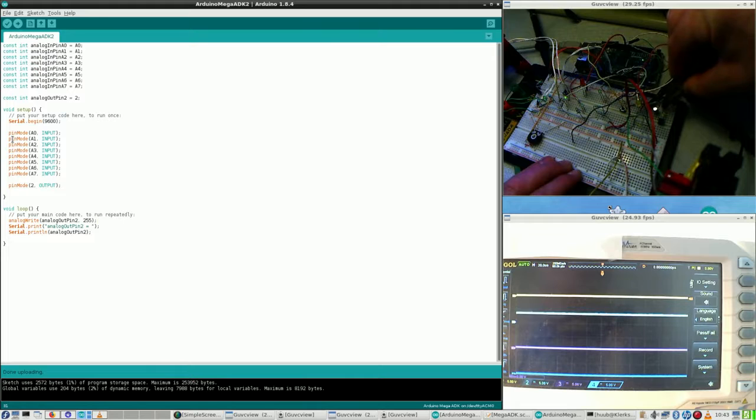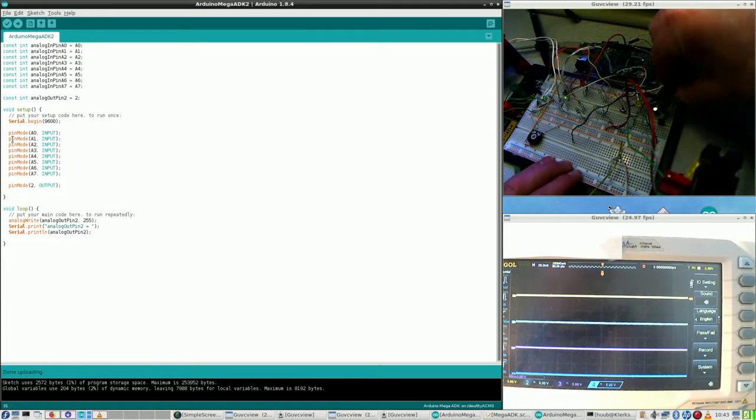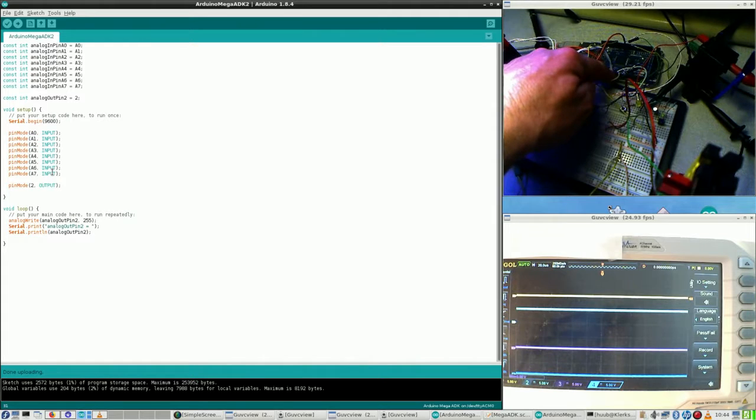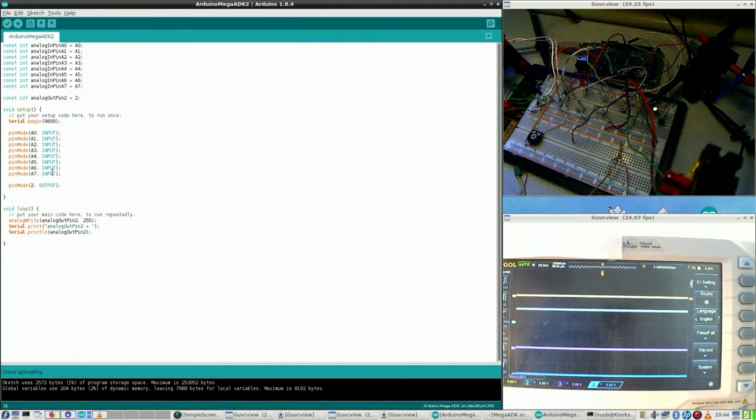Yep. This simple check means that there is something not quite alright with the definition and with the output ports, because this is defined as input while it is acting up as an output, and that wire is A5, if I am correct. Yeah, A5 is acting as input, as output actually. This is very wrong.